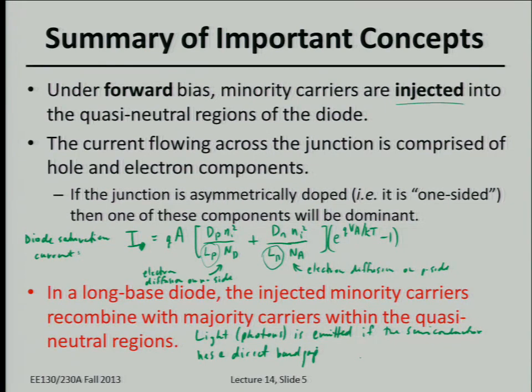In other words, you can have an electron and a hole recombine without a trap, so an electron can lose enough energy to generate a photon in the visible wave spectrum. So technically this should be visible light. Silicon, an indirect semiconductor, could emit light if you go from the trap to the valence band. It's just that you're not going to see it. The wavelength's too long.